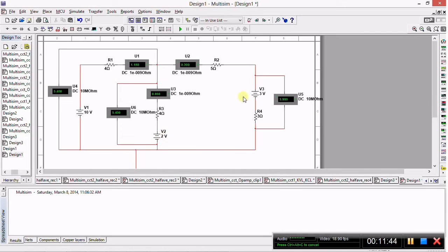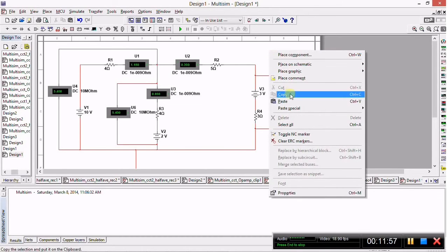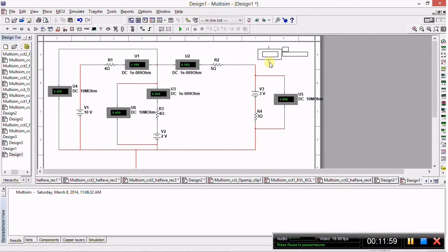So now that this is a second loop, we know that this potential drop across the battery as well as the 5 ohm resistor should be equal to 5.4 volts as well. So now I'd like to drop another voltmeter on the work area. Since we already copied it before, it was already there to be pasted on the clipboard. So we'll just connect the terminals across the 5 ohm resistor, and then we will run the simulation again.